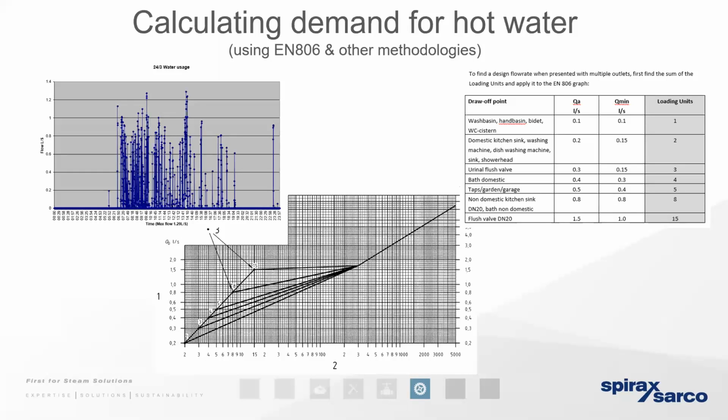What we want to ensure is, if we're helping a client move away from an existing storage heat exchanger towards a modern and efficient instantaneous plate heat exchanger, perhaps the very worst thing we can do is take the badged duty off the older heat exchanger and carry it across to the new heat exchanger.